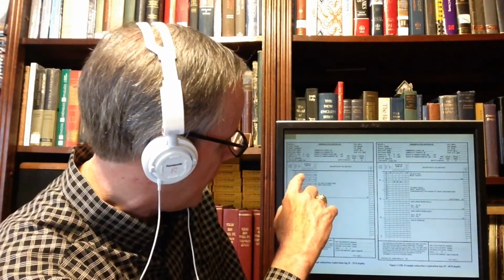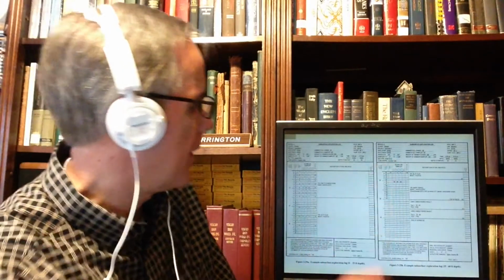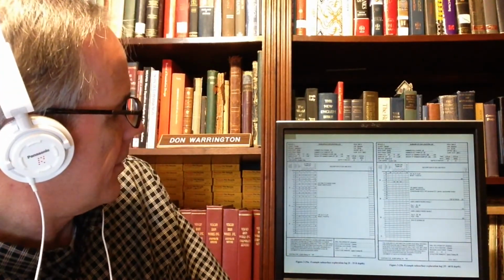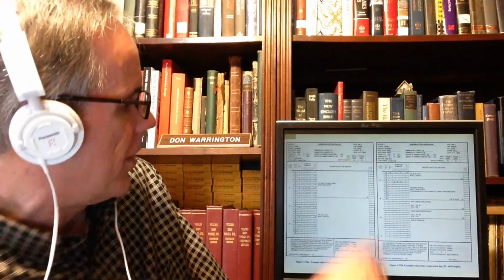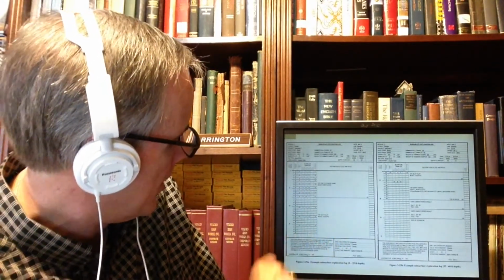You'll notice on this soil boring log, the SPT values go this way, horizontally. You'll see the water table locations somewhere on here. Sometimes it'll be up here. Let's see, depth of water right here. Sometimes they'll put the little indicator, sometimes they won't. Again, you have to read a boring log carefully, and it's hard to teach. It's one of those things where it's a lot easier just to do it to learn it.